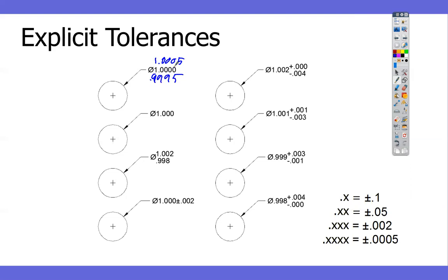On a regular one, it's plus 5, minus 5 ten-thousandths, right? It's 4 decimal places. I'll get the 4 decimal place one. It's that. So I just added 5 ten-thousandths, subtracted 5 ten-thousandths. What's the tolerance on that one? It's plus or minus 2 thousandths, right? So that means the size could be 3.002 or 2.998. And then the rest of these, they have tolerances called out.